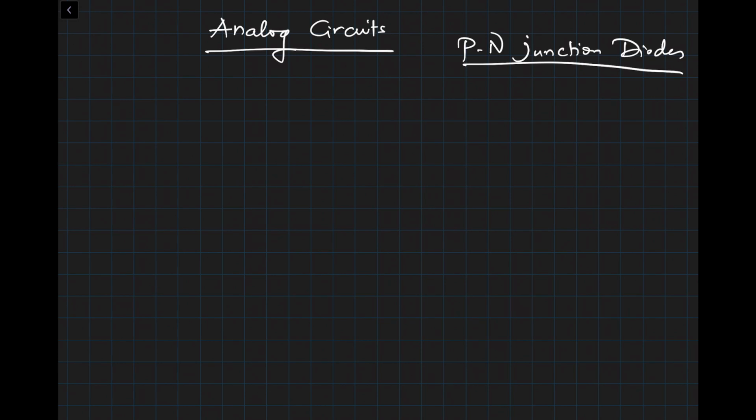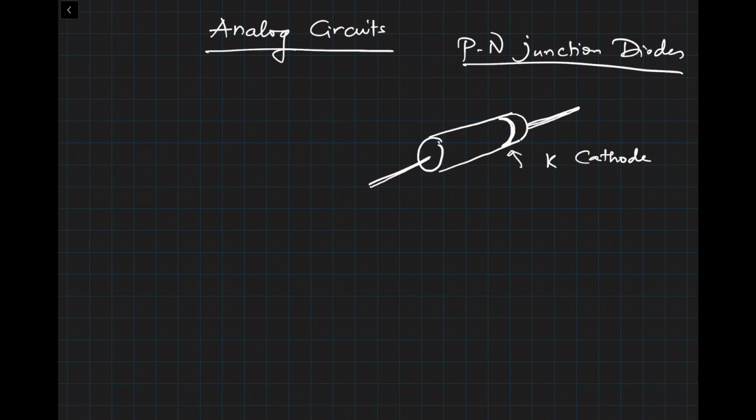Just a few minutes ago I showed you a diode in the lab, and I was trying to describe it to you. Here is a diode that you can buy as a component, and it looks like a cylinder, with a terminal coming out of it. In the one I showed you, it had a white or silver ring on one side, and this ring generally denotes the cathode, K. If that is the cathode, then the other terminal is the anode.